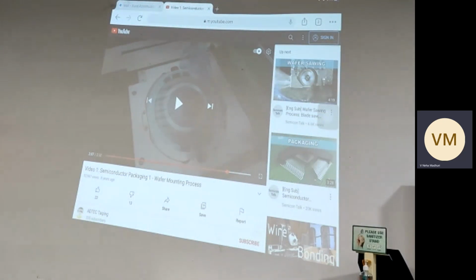So what we can do there is directly connect on the wafer and do measurements. Okay, we take a pin and connect directly, let's say from the power supply, we take two pins, one on the gate and one on the drain and one on the source. Then we take out one pin from the function generator and put it on the gate side, right? That kind of packaging.